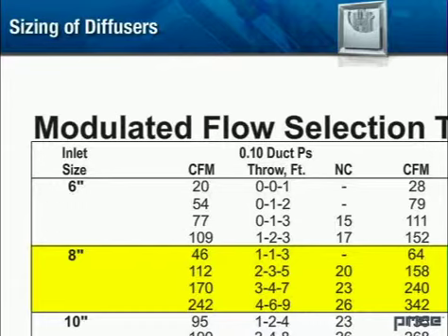Upon selection of the appropriate diffuser size, note the lowest air volume cataloged under the duct pressure column. This is the minimum limit of the diffuser at the listed static pressure. Assure that throw, noise, and air volume meet the required specifications.